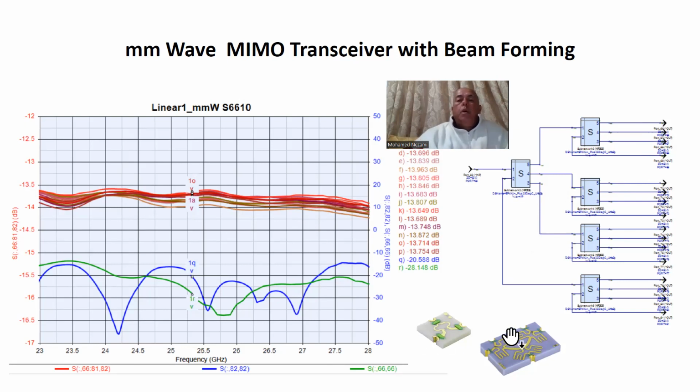These are thin film 4-way dividers. They are available from Knowles and from many circuits. And this was cascaded in here, and this is the performance we got based on the S parameters provided by the manufacturer. So we're going to use this as the feed design. Now, you could, if you want, design this as Wilkinson dividers and use no parts like this, just stripline with thin film resistors embedded. But it's up to you. I just chose this because it's simpler, just for the heck of it.